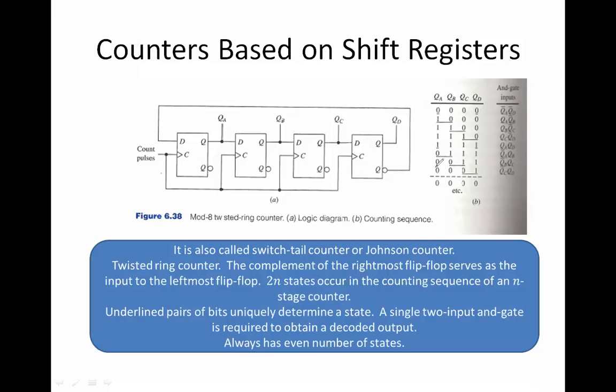So now let us see the values that are here. Initially if I feed 0 0 0 0, that is my initial value. So what is going to happen is QD is 0, so QD bar becomes 1, so that is here, you can see, 1, and this 0 is pushed here, and then this 0 becomes 1.